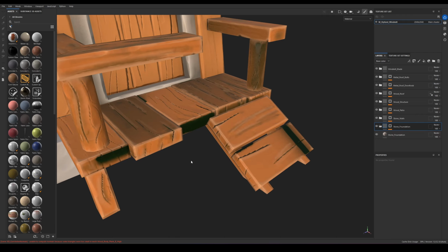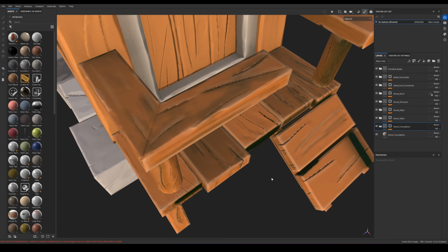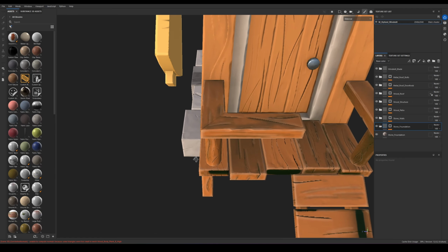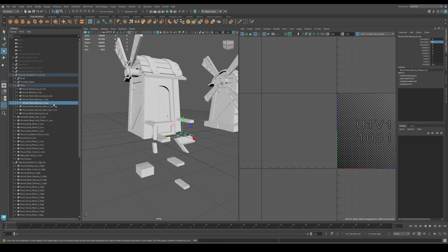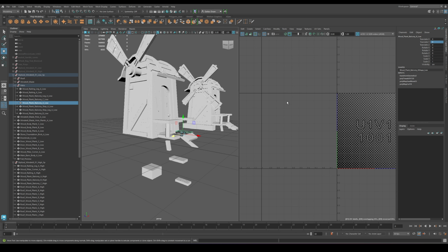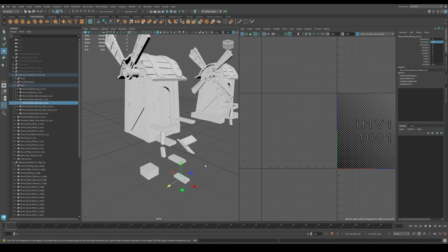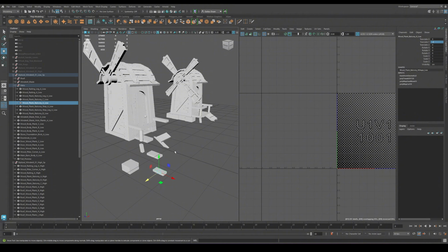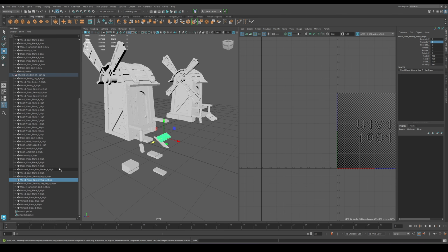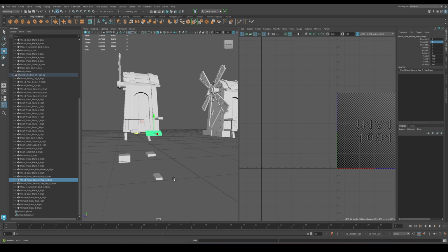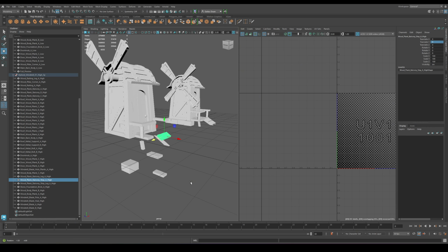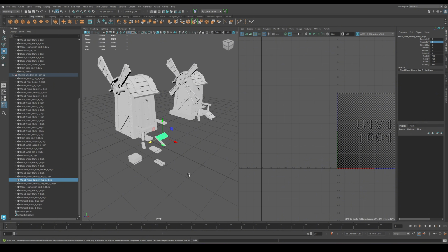Now the second major issue was the overlapping artifact from baking. To fix this, I went back to Maya, looked at all the assets that were causing issues, and moved them away from the crashing geo to get cleaner bakes. Reminder, you need to do this in your low poly, and then make sure you move the matching parts in your high poly as well.